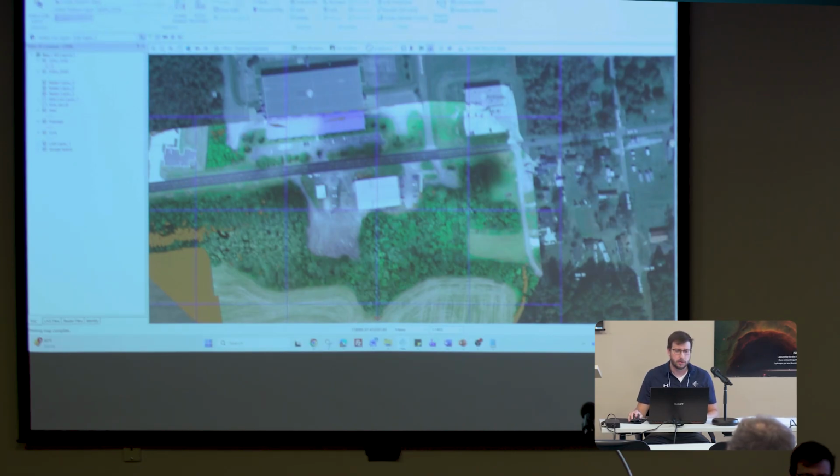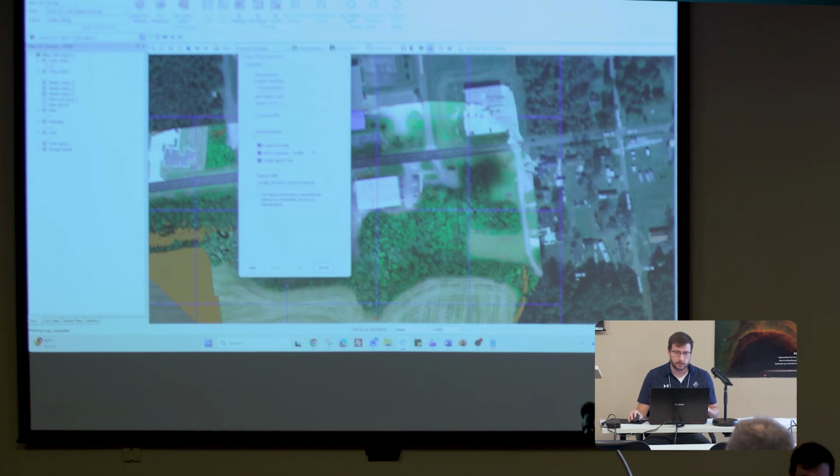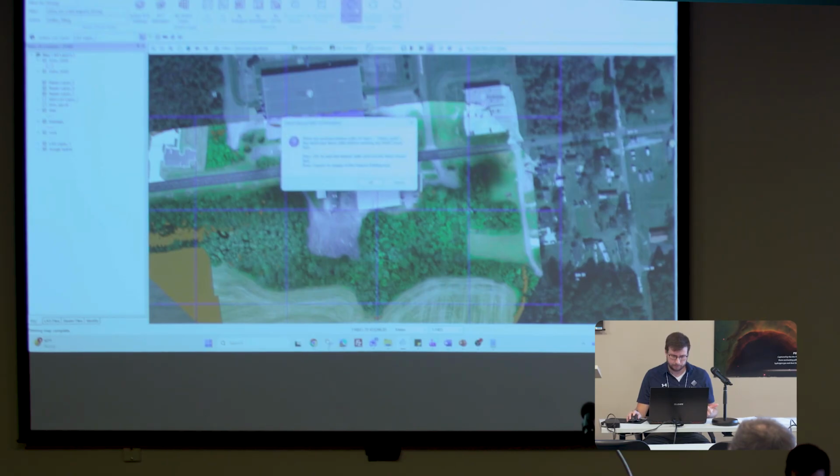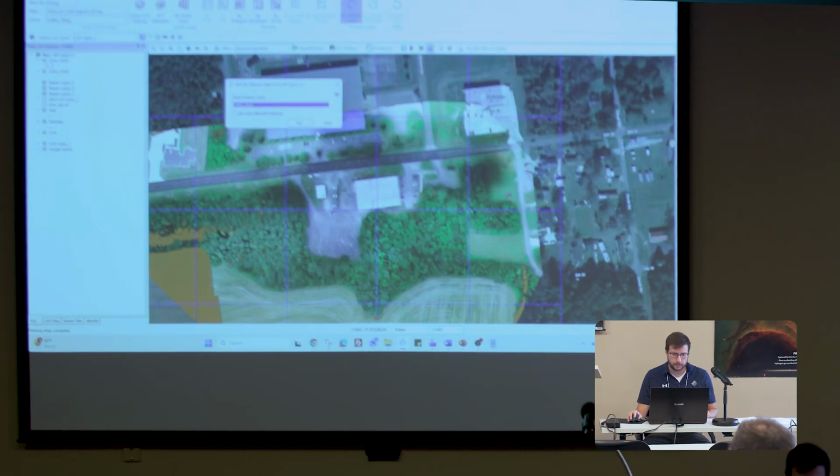So click on point task at the top. Click on ortho tiling if you want to go with me. Click on active PCT settings. And basically this is just running exactly the same thing we did before. This is that convert raster PCT, but we're using that. We're going to run by feature layer, and then we can run on the individual tiles to chop this ortho up. So go ahead and run by feature layer. Click OK. And then run on the ortho grid too. Click run.